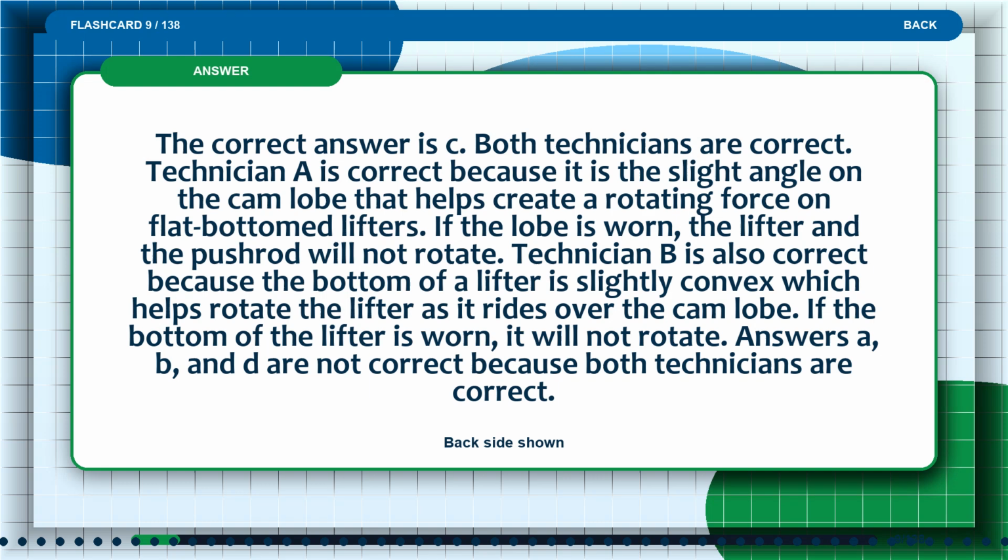The correct answer is C. Both technicians are correct. Technician A is correct because it is the slight angle on the cam lobe that helps create a rotating force on flat-bottomed lifters. If the lobe is worn, the lifter and the pushrod will not rotate.